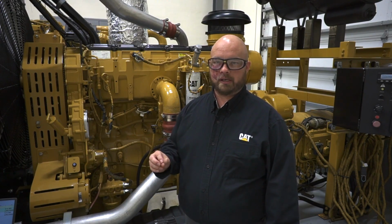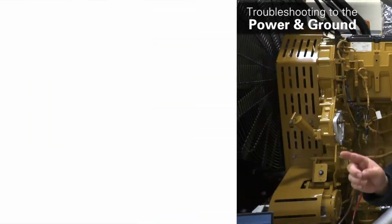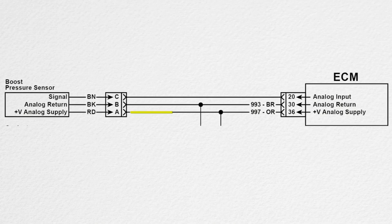The scenario we're going to go through is we have an active -4 FMI voltage below normal code. Okay, so the first step that we are going to do when we have any problem with any active sensor is check for power. On this 3-wire sensor, the A wire is our 5-volt analog supply coming from our ECM. The B wire is our return, also provided by the ECM, and the C wire is the signal from the sensor going to the ECM that's giving us that variable DC voltage that we're looking for.